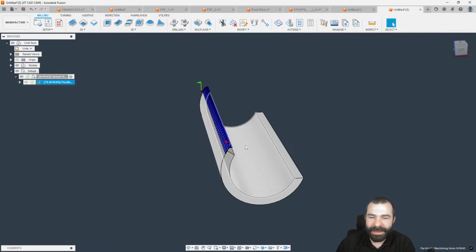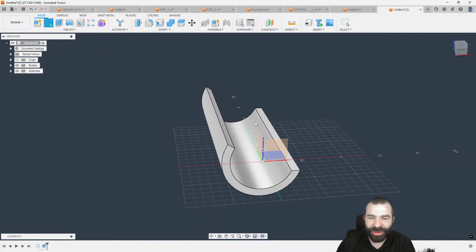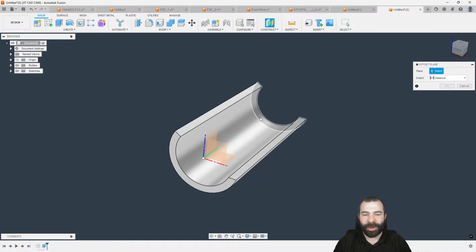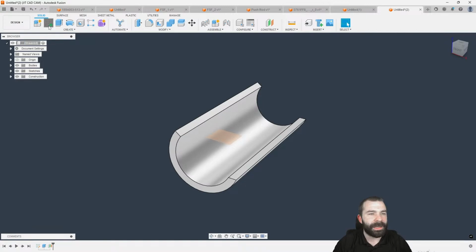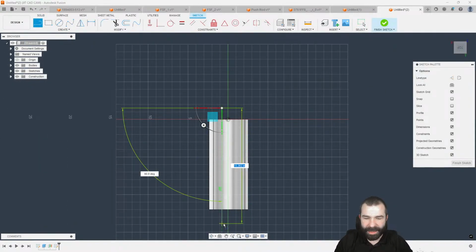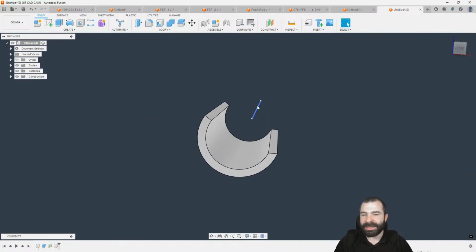So what we ended up doing, if I remember correctly on this, is we went back to design, and I think we created a sketch, if I oh so certainly remember. And we actually did a sketch by offsetting this up in the air a little bit. What you're seeing me do is I'm putting a plane higher up. We've created that sketch, and then I'm going to just drop a line down my part. Now, the idea is this line, we're going to use this to control from the center line of our tool outwards. Travis, if you want to send it over to me, yes, please.